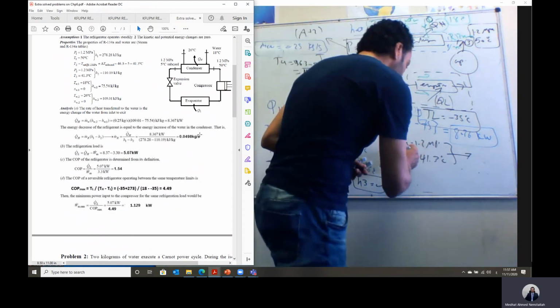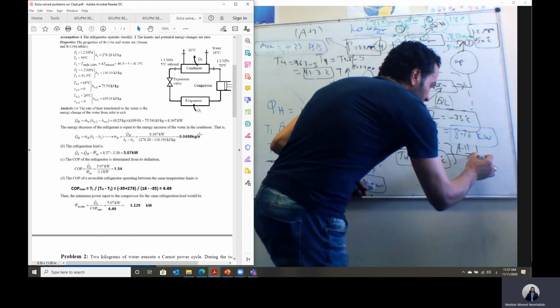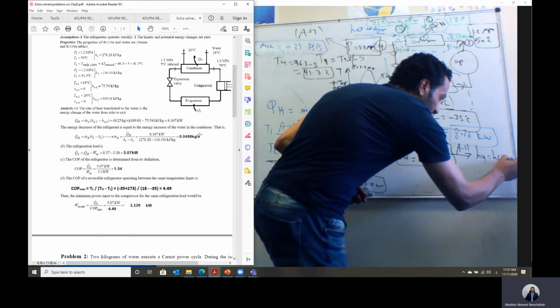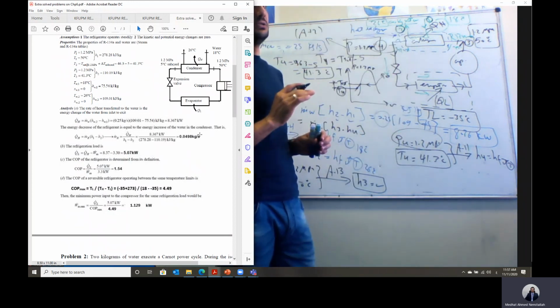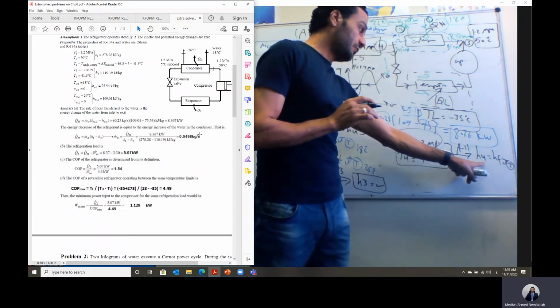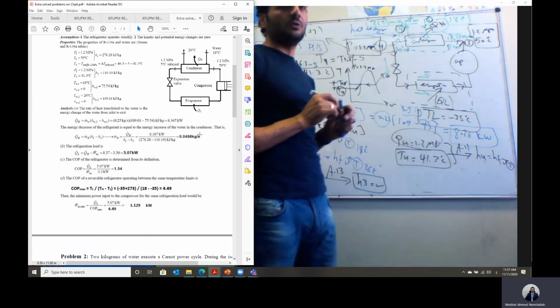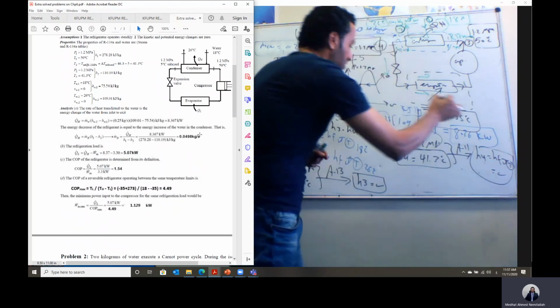So in this case, using this temperature, I will go to table A11, then H4 will equal h fluid at this given temperature, not given pressure. I have to repeat this again, there is a big difference. So the enthalpy H4 will equal h fluid at the given temperature from the temperature table, table A11. Then we can get the value of H4.